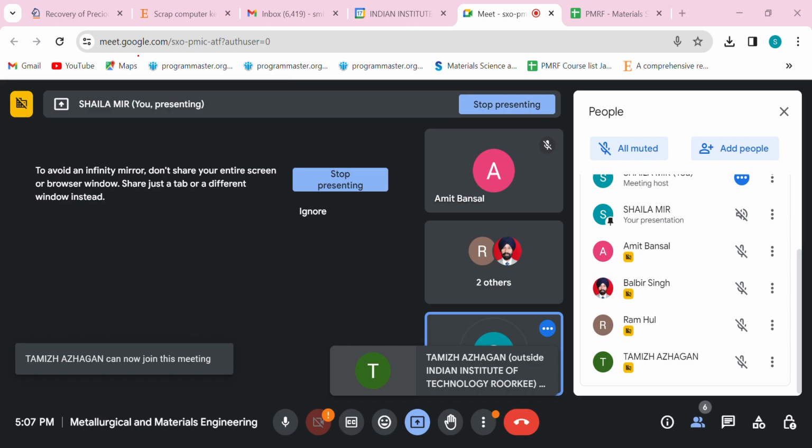So we also have another question that says a composite is developed using glass fibers added to a polyester matrix. The tensile strength of the glass fiber is 1800 MPa, and polyester is 55, right? So you are given two types of materials. You have a matrix and you have fibers in it, and you are given the strength of both. Glass fibers are 1800 MPa, obviously because it is a ceramic material, so it will have higher strength, while polyester has 55 MPa.